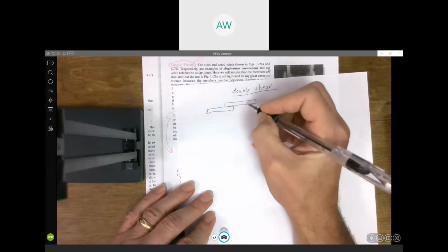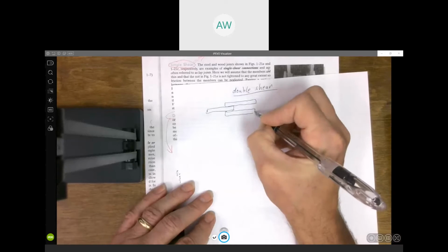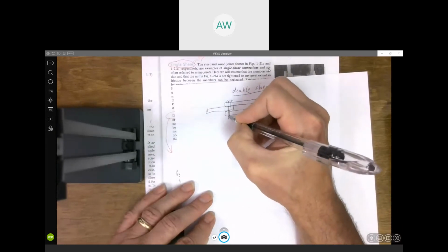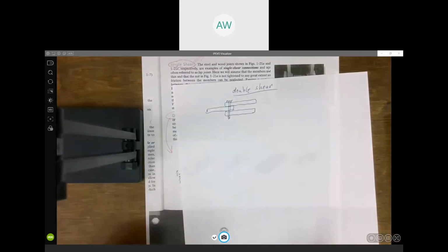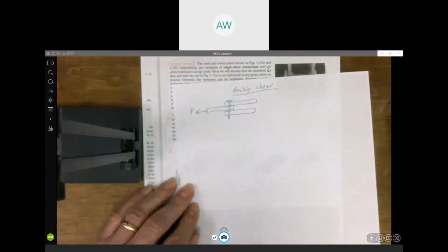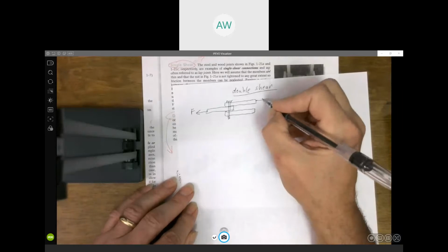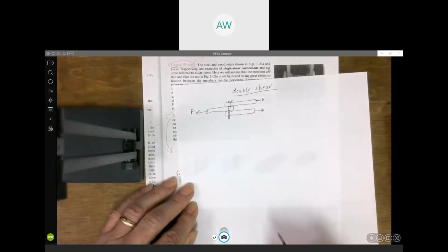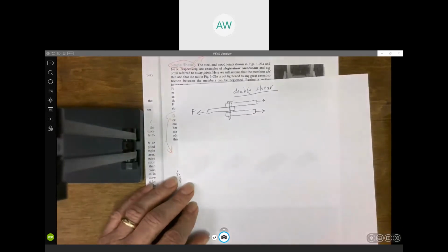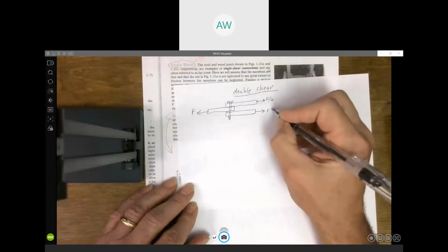Instead of just having, say, the 2 plates like that, now we actually have 3 things that are joined together. And if we apply some force F here on one plate, again, the forces have to add up to 0. So if we've got F going to the left, we got to have F going to the right. So each one of these would be F over 2.